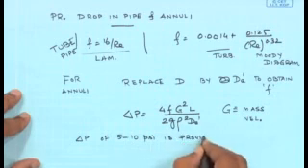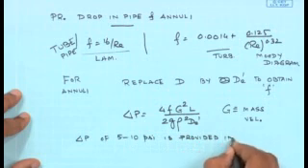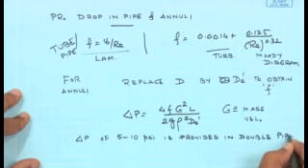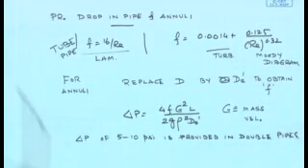provided in double pipes. So, once again to calculate the pressure drop, we can use the same relations that we have used for calculating the pressure drop in a pipe. For the case of annuli, we replace the diameter by the hydraulic diameter, use the same relations. The pressure drop can be expressed by the standard formula that we have done in terms of the velocity, or it can be expressed in terms of the mass velocity.